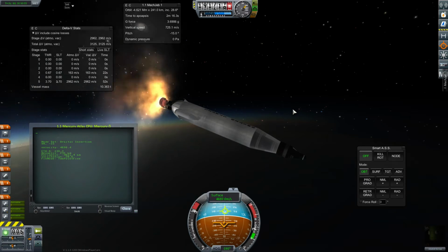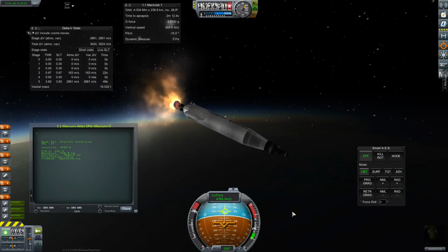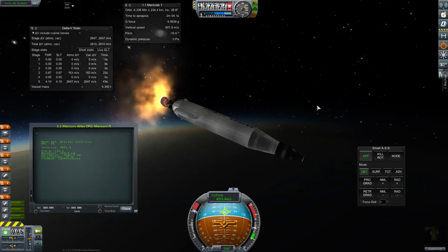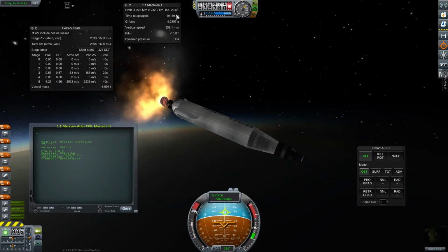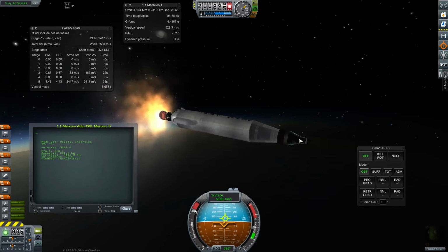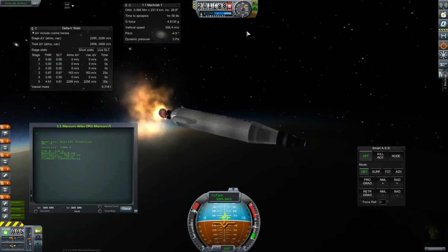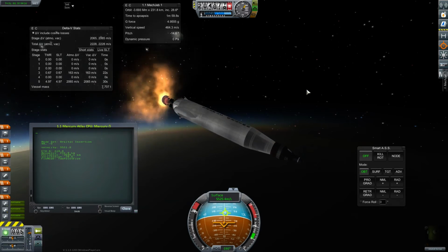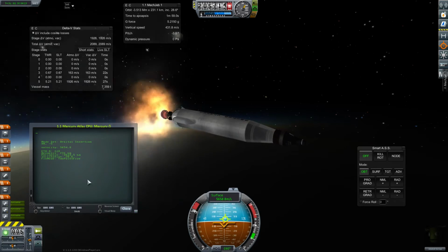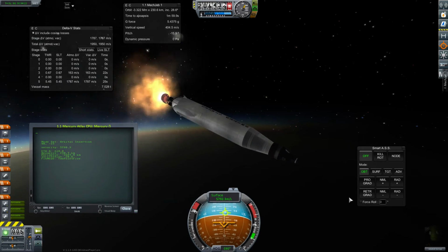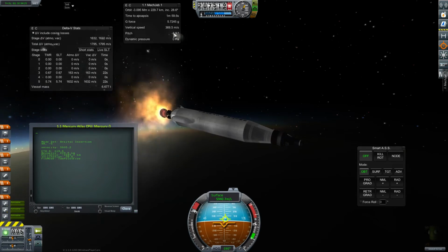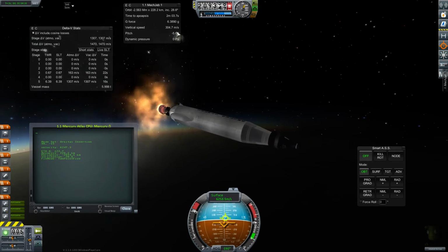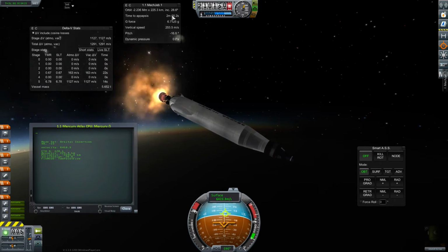And the thing I don't like about the stepwise functions is what you saw right there. It pitched down just once. It makes that judgment every loop, so a couple times a second, where it's looking at this number and checking this. But these are discrete outputs. The pitch is -15 or it's -5, etc. It's making these judgments in quick time cycles, like a PID would, or just a program. It keeps running through the program as quickly as it can. But these actual outputs are discrete. It's either -15 degrees, 5 degrees, or 1 degree, depending on what it sees as this time.